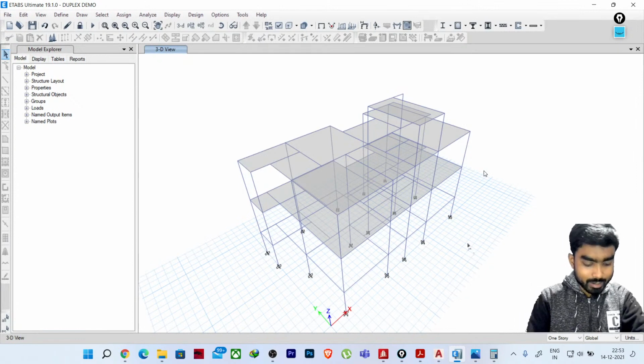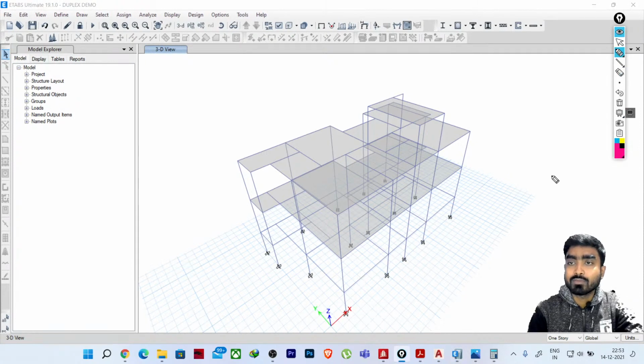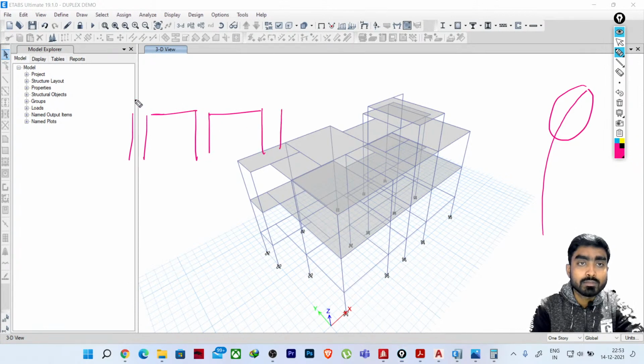Yeah, you have got high rebar at the top stories. When you have earthquake load, you will be having high reinforcement at the top stories, because I will just explain it in a very simple way. The column will be going like this, right? So in that case, the unbalanced moment used to be very high at the top. The unbalanced moment I have just talked about. Suppose in case of gravity, you have a column, you have a beam, similar span, right?